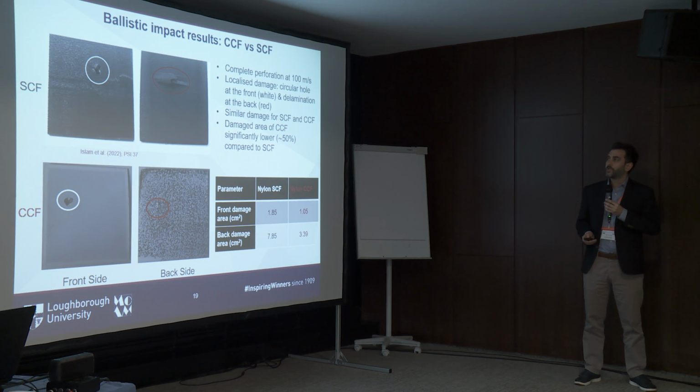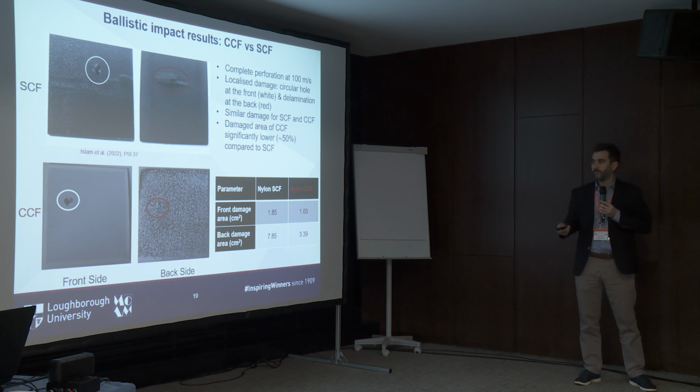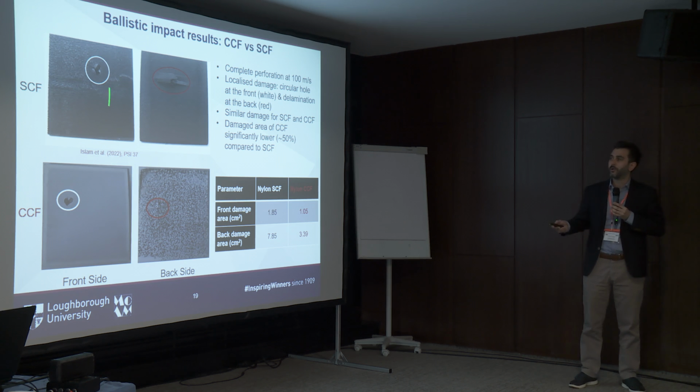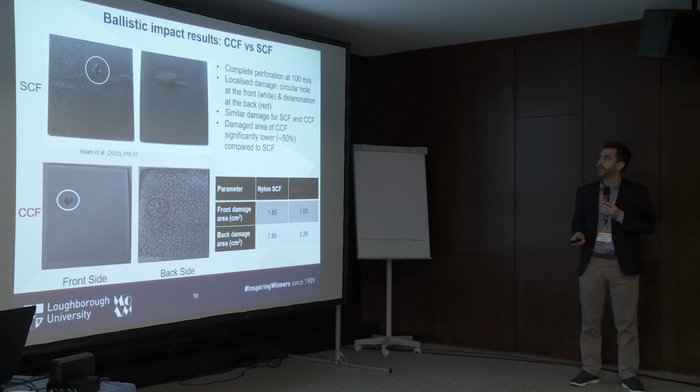So these are some results. Post-mortem plates. Again, on the top is the short carbon fiber plate. On the bottom is the continuous one. This is the front side, this is the back side. The obvious thing is both plates failed, okay? They did not perform very well with this thickness, complete perforation in this range. The damage is localized at the front, and then you see the delamination at the back.